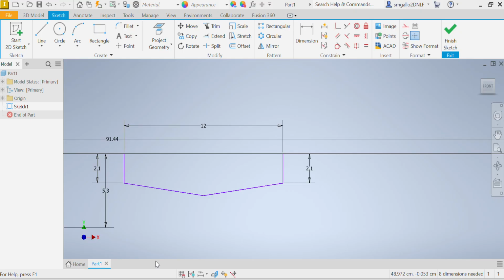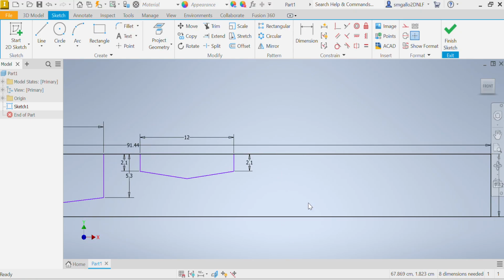The vertical stabilizer is one that I want to make sure I show you. I am keeping in mind that the grain of the balsa wood goes from left to right. So the leading edge of my vertical stabilizer has to be oriented the same way. My typical vertical stabilizer will look like this.